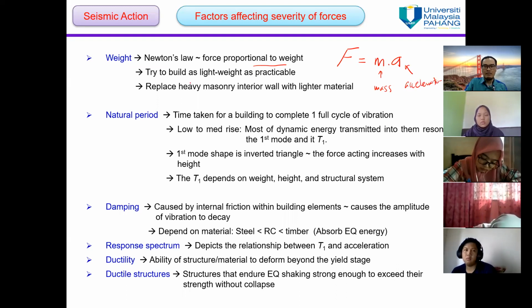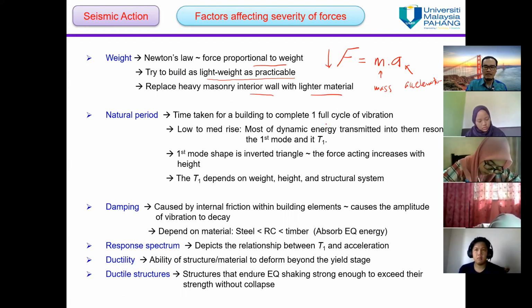So we must try to build as lightweight as practicable in order to reduce the forces, because it is proportional to the mass. So we can replace heavy masonry interior walls with lighter material.